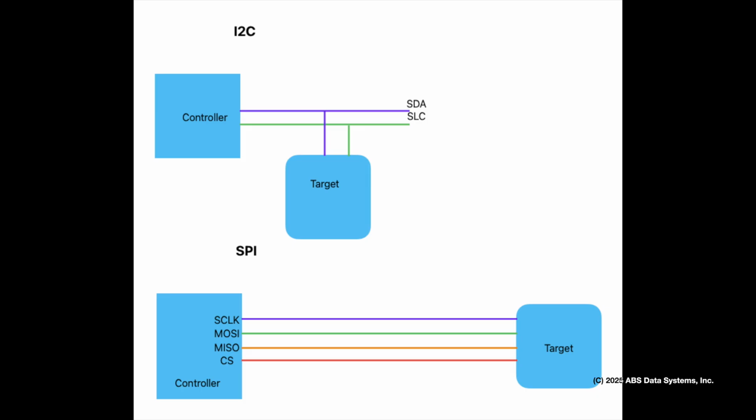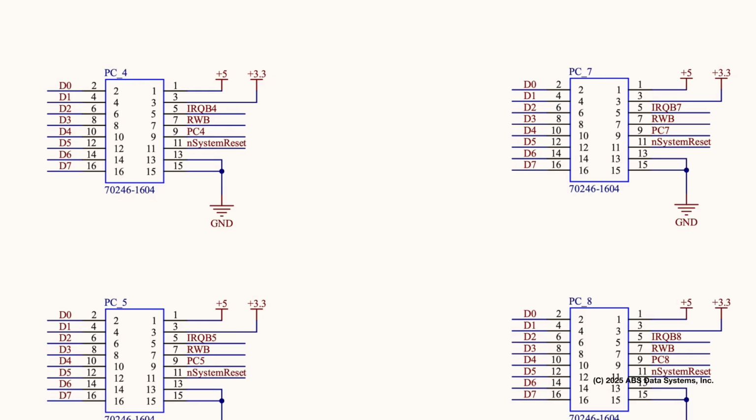SPI and I2C use fewer pins to connect devices together and a clock to transfer one bit of data at a time. We are not running that fast, nor do we have the extra hardware already built into the processor. Therefore, I've elected to transfer the entire 8 bits of data all at one time. That's not to say there isn't overhead associated with transferring data. I have created a protocol to synchronize the data between the devices.